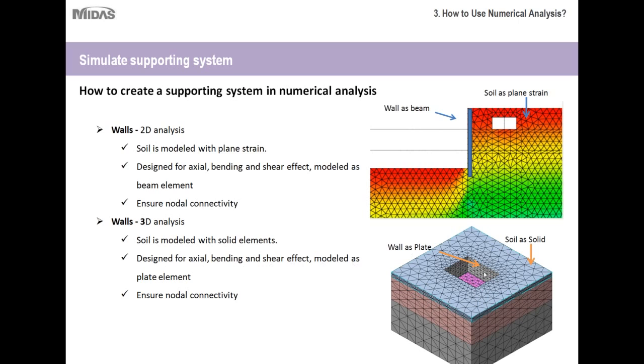If you look over here, the mesh in this area is a different color than the mesh over here. This is just to let us know that this mesh consists of a different material property than this mesh. This mesh obviously represents our retaining wall, and it's where these 2D properties and the material property have been applied to it. Later on, when I show you the demonstration of the project, I'll get you a better view of what that 2D planar element looks like.